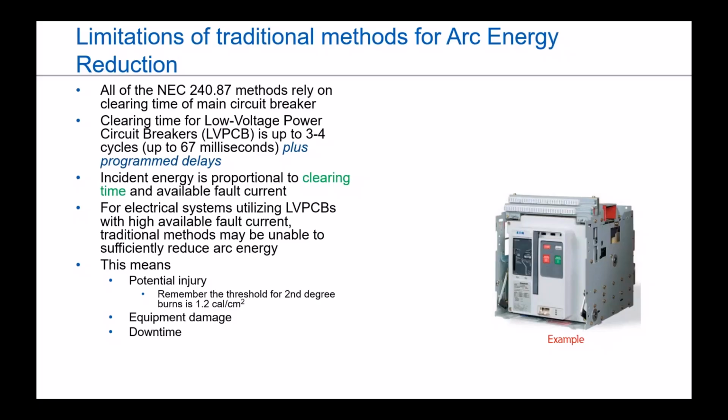Well, that means your clearing time is kind of always going to have a floor that you really can't go past. And that's just assuming there's no delays. If you have delays, it's even worse. So for any system that's using them, particularly if there's a high fault current available, sometimes you could run into issues where some of the traditional methods aren't really getting you to where you'd like to be.